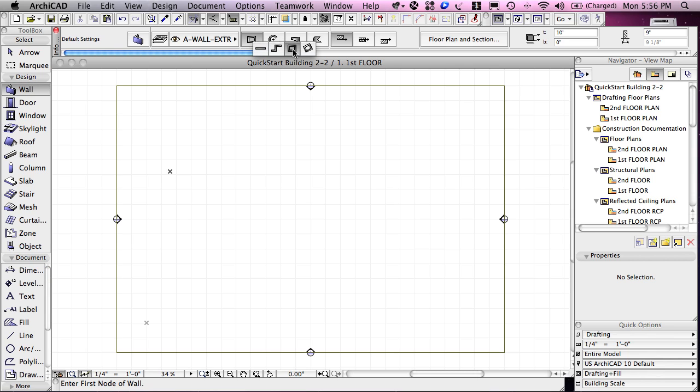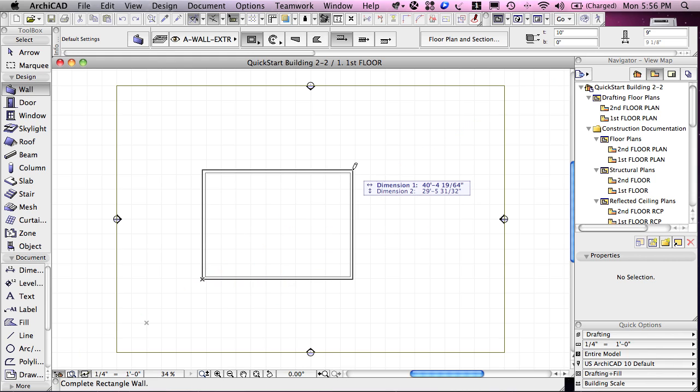When I select that geometry method and click to start drawing, you'll see dimension 1, 0, dimension 2, 0. And as I move, you'll see dimension 1 show the horizontal displacement, dimension 2 the vertical. And as I mentioned earlier, to make it a specific size, one of those dimensions is highlighted. You notice it's actually bolder. That's dimension 1. So if I want to make it a certain size, say 50 feet, I'll just type in 50. That would be about 15 meters.